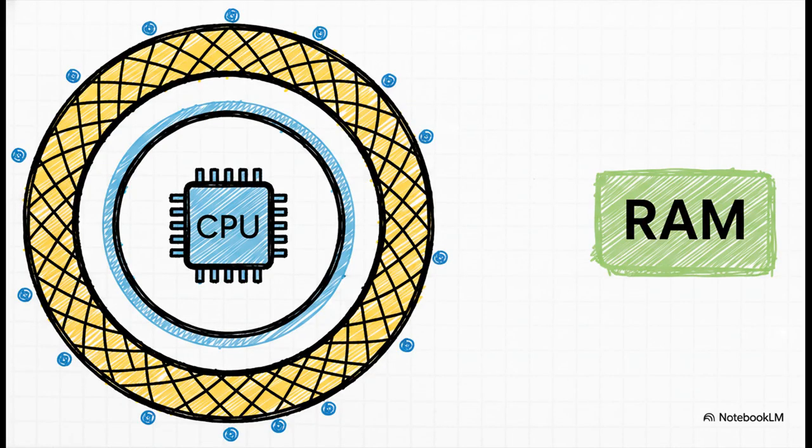And backing up that L2 cache, modern systems usually pack a Level 3, or L3 cache. This is your final vital layer of on-chip memory. It dramatically reduces those L2 misses and acts as the ultimate safety net before the processor is forced to trek all the way out to the incredibly sluggish system RAM. Plus, in modern multi-core systems, while L1 and L2 are mostly dedicated to single cores, this massive L3 cache is generally shared across multiple cores working in parallel, requiring some really brilliant traffic management to avoid contention.